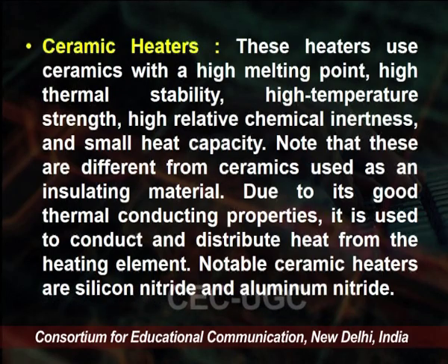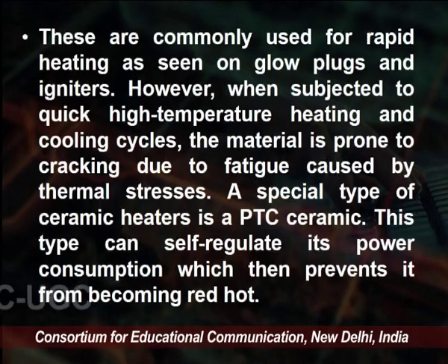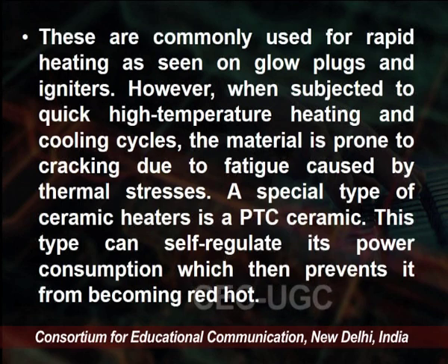Due to its good thermal conductive nature, it is used to conduct and distribute heat from the heating element. So ceramic heaters are silicon nitride or aluminum nitride, and these are commonly used for rapid heating, as seen in glow plugs and igniters.